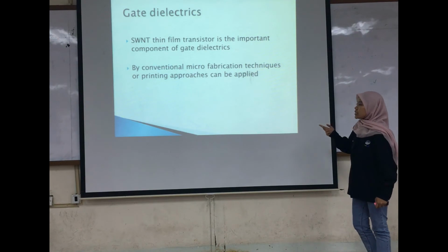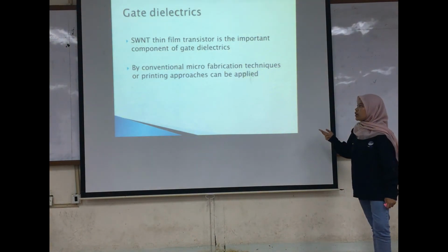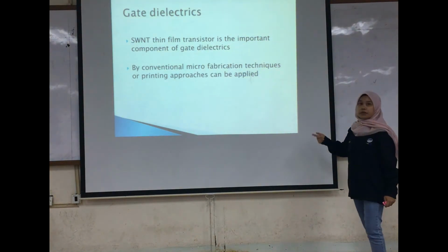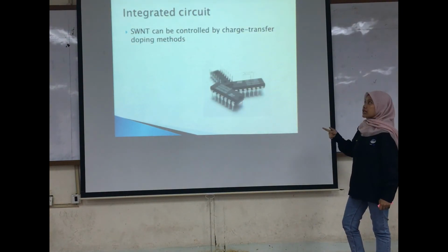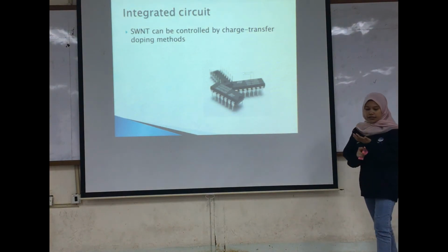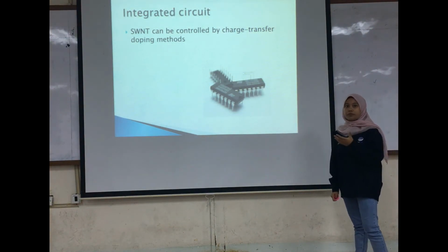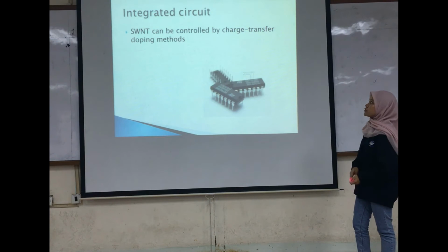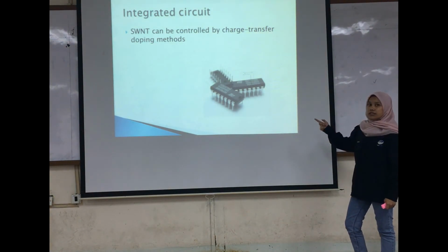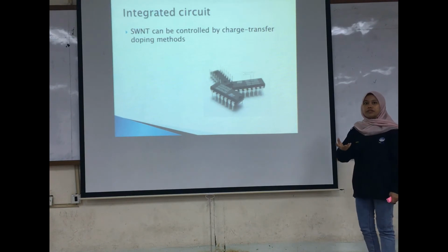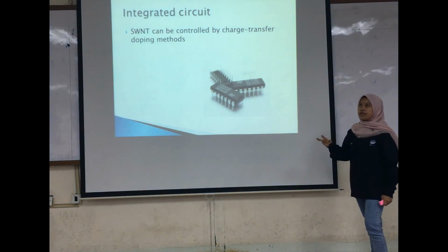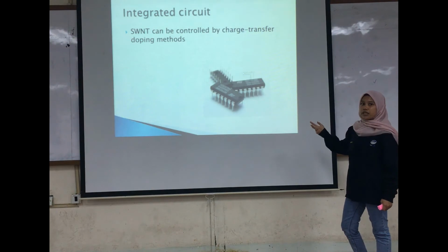Conventional microfabrication techniques or printing approaches can be applied. Integrated circuit: since the polarity of single-wall carbon nanotubes can be controlled by charge transfer doping, CMOS, complementary metal oxide semiconductor, which is a type of inverter, can be constructed.